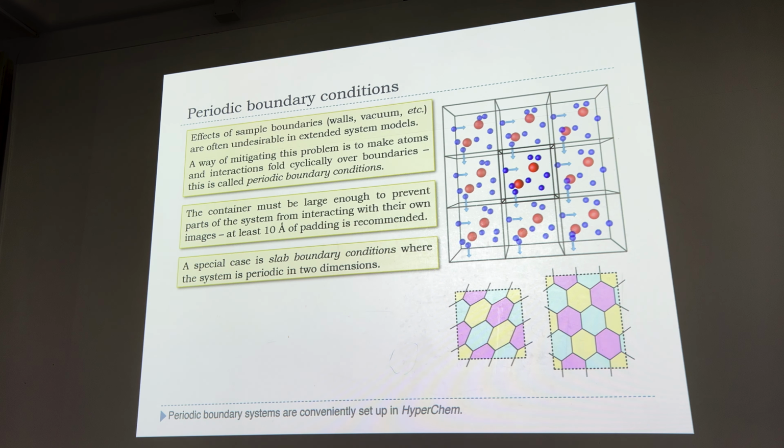Again, in Gaussian, these things are automated. If you click periodic boundary conditions in GaussView, you will be able to set them up. What is important, of course, is that it's not just atom positions that we will be optimizing in this case. Even the dimensions of this unit cell become adjustable parameters.